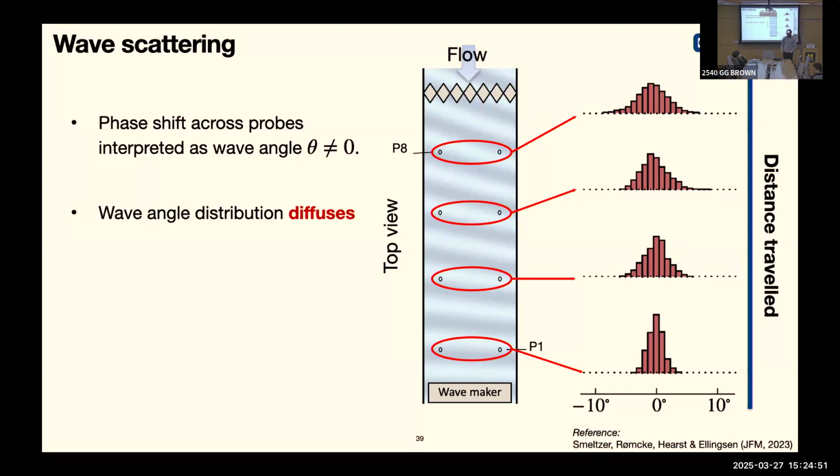Do your waves have time to reflect off of the relative greater angle from the outside? It's a good question. So this is done as ensembles. We start the facility with running water, which does a lot to stabilize the surface. Then we send a group of waves up and we measure. As soon as the reflection starts happening, we stop the experiment. And then we do it again 100 times. It takes a long time.